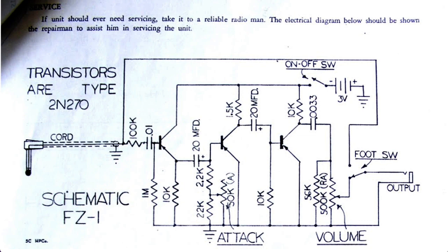Anyway, this particular version of the FZ1 consists of 3 transistor stages. Now, these stages are using PNP transistors instead of NPNs as we've generally been looking at in this class. But to draw the schematic as if we would typically draw NPN circuits, namely having the emitter at the bottom, they actually put the negative power supply at the top.